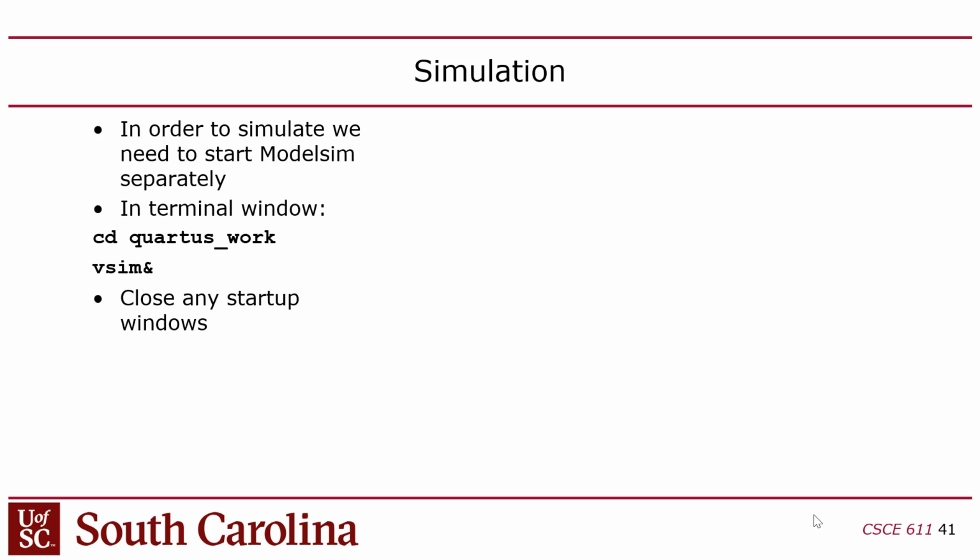There are open source alternatives for this, namely Verilator and Icarus Verilog. However, those are even harder to use than ModelSim. And Icarus doesn't support SystemVerilog, so we can't use that. And Verilator only supports two-state logic. So a logic signal in Verilator is just a 0 or 1.